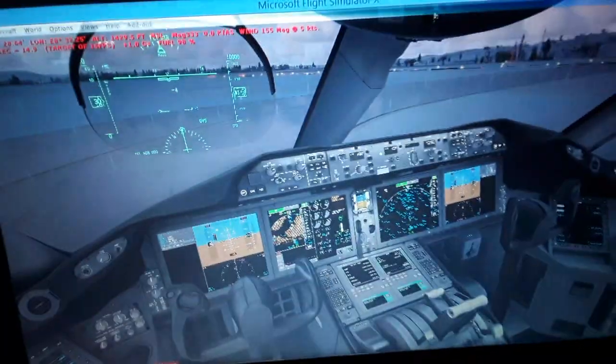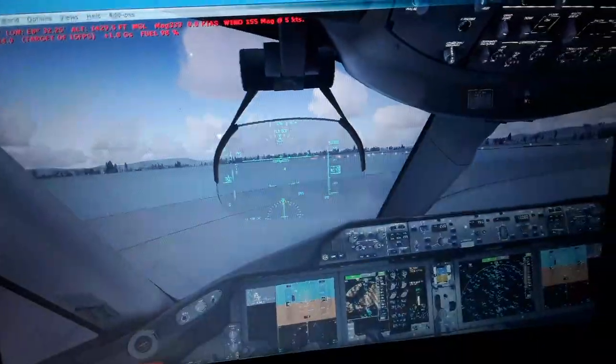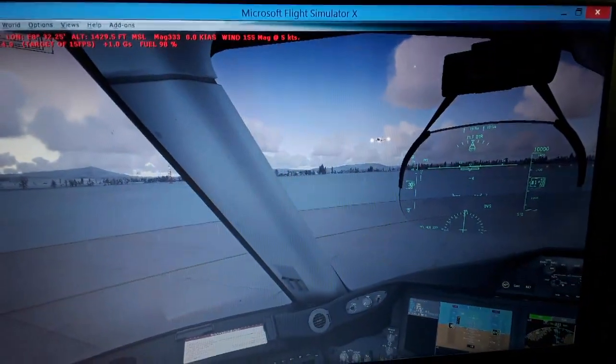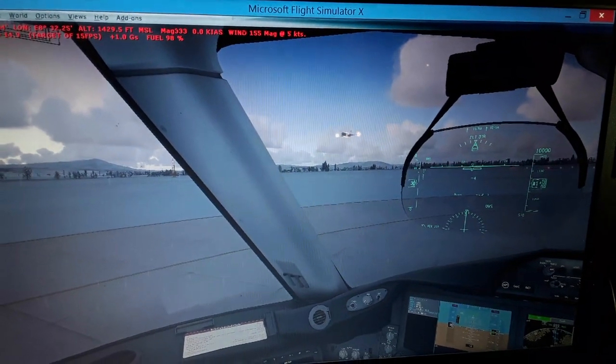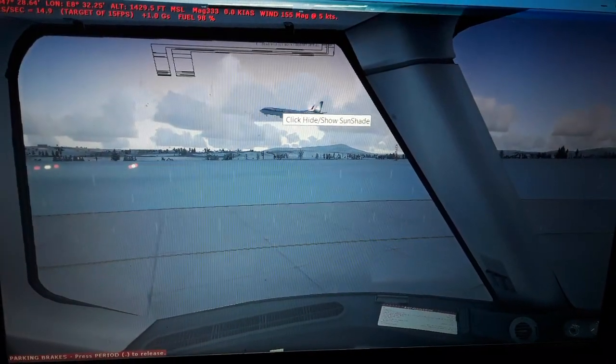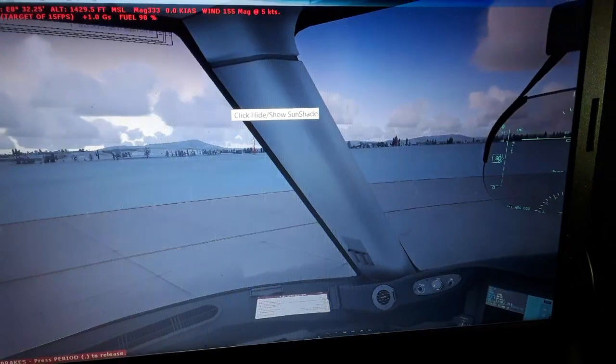and the horizontal trim stabilizer for takeoff and for flying is calculated automatically, since this is a fly-by-wire aircraft. We can use the flight management computer to make calculations about the center of gravity as we fly. The center of gravity of the aircraft is calculated from the flight management computer automatically. Also, as we fly, we burn fuel, so the center of gravity shifts and is recalculated automatically.